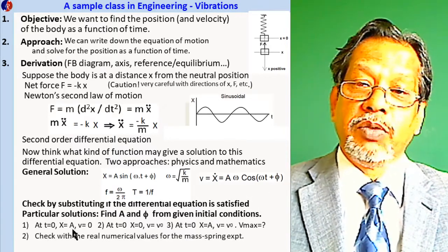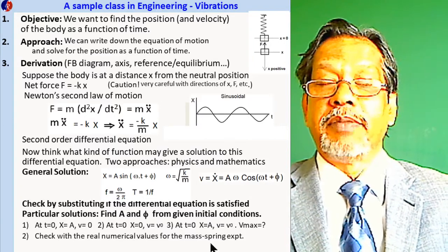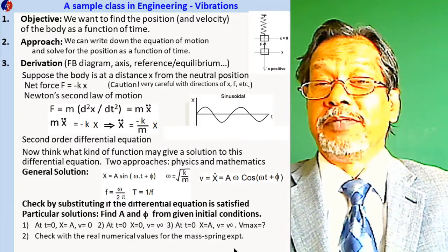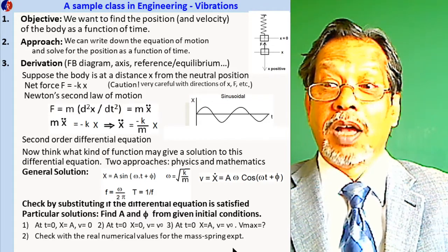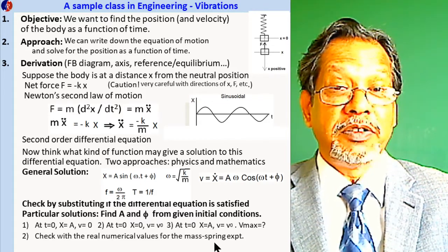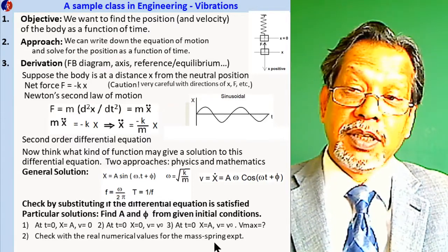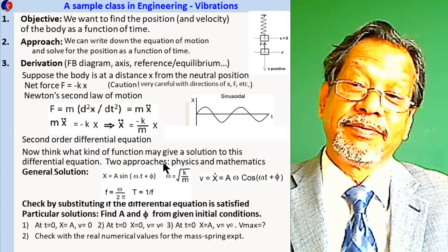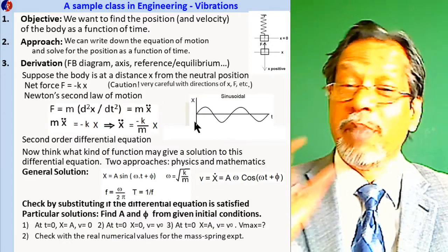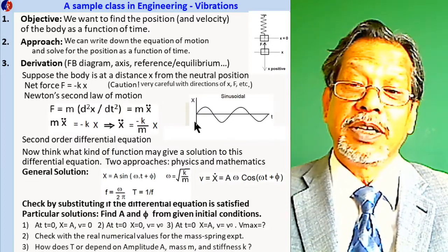All right, check with the real numerical values for the mass spring. If you brought a mass and a spring, ask them to plug in those values, the value of the mass and the spring constant, and see if the calculation matches with the measured ones. That's going to be really exciting for them.